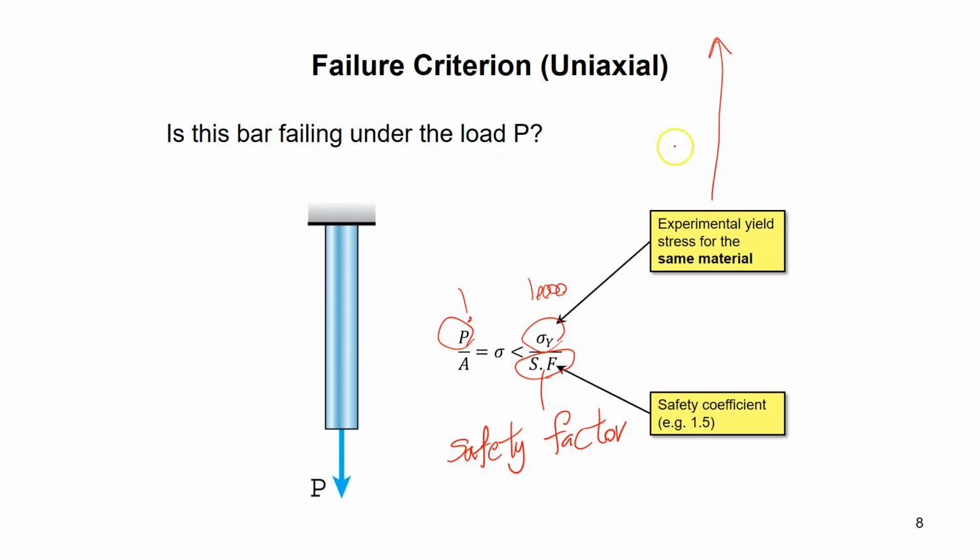You would see a range of numbers where it might have a normal distribution like this. Here, this is the number of the samples that you found having that value of sigma y, and this is sigma y. The average might be something like 10,000, while the lowest one could be like 9,000, and maybe the highest one 11,000. So you never know exactly which one of those you will get out of a manufacturer. And this is all assuming that they are telling the truth.